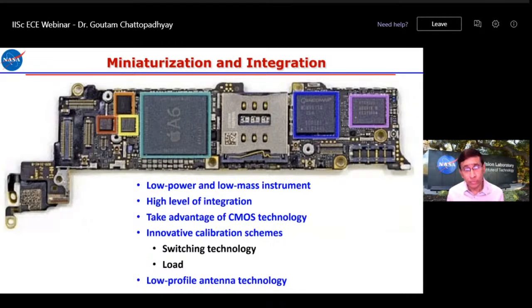One of the ways we do it, since it's a radiometer and spectrometer, is that there are two temperatures, very well-known temperatures. If you look at two temperatures and basically two levels of signal, then we can compare and say, okay, this is the gain of my system, and this is the detection level that we are going to get. Because as I said, for the phosphine case, it was 10 parts per billion, and sometimes we measure parts per trillion as well with this kind of sensitive receivers.